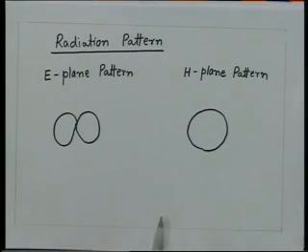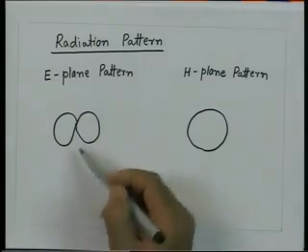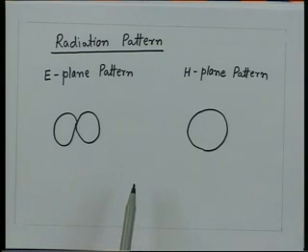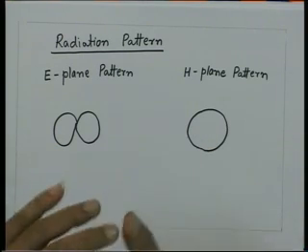But we should always remember that although normally these two sections of this 3-dimensional figure are given as radiation patterns, the radiation pattern is actually a 3-dimensional surface. That should always be remembered, because many times if we do not remember that, we might come to wrong conclusions, and that we will see a little later.